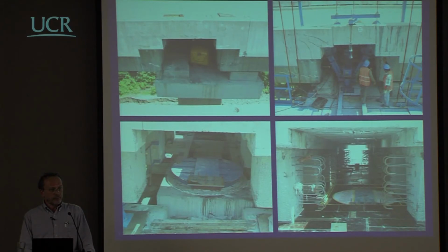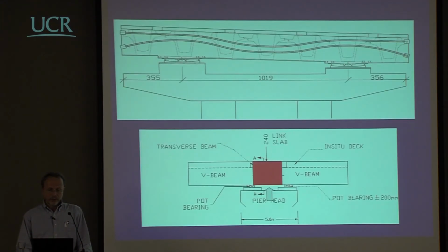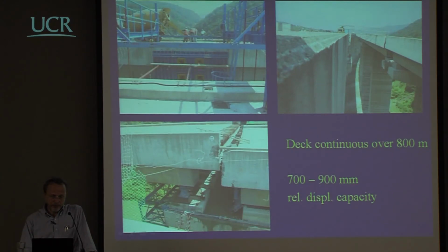And these are the connections between the existing beams and the new beam that will be cast here, including the bolts that are connected to the upper part of the bearings. And this is what happens if you look in terms of the transversal beam. These are the actual cables, and this is the position of the transversal beam. And here you can see the heads of the transversal cables. And here you can see one side of the bridge which has already been moved up, and the other one which has not yet been moved.